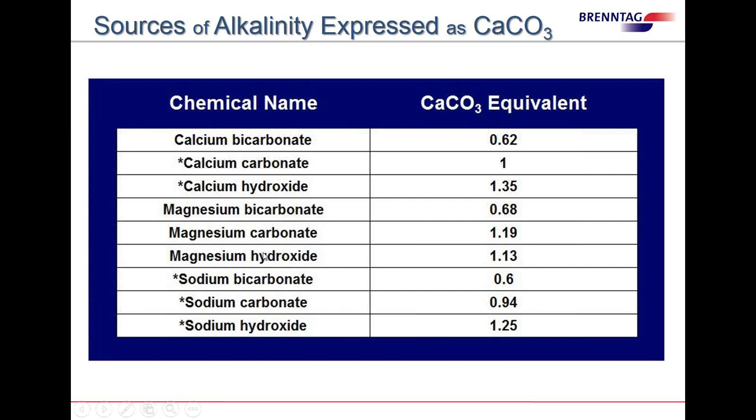A lot of the chicken kill rendering kind of people are using magnesium hydroxide. Now, I love magnesium hydroxide because it has a very good capability to put alkalinity in the water, and also magnesium is a fantastic nutrient for bugs. So you're not going to get an argument from me if you're wanting to use that.